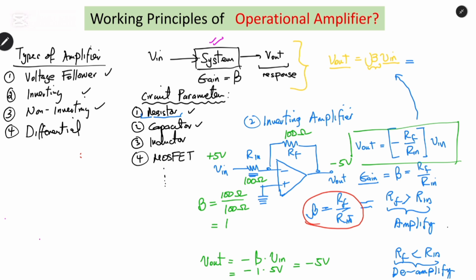And this is similar to a voltage follower circuit, having the inverted portion that makes it unique. For the voltage follower, if we have these two values of the resistor being the same and we want the output to follow the input without inverting, we can simply remove the resistor connected with the inverting terminal and connect the input to the non-inverting terminal. Then you will have it.